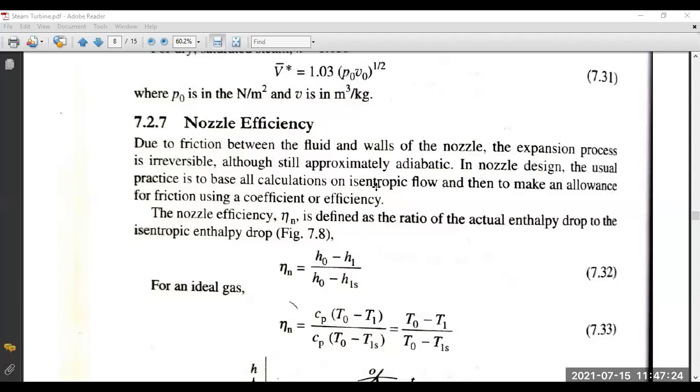This common point is where we get the enthalpy and the entropy of the stagnation point itself. So first we plot P0 from the Mollier diagram, then the P1 curve, and we put the curve of the temperature T0, and at the intersection we get point 0, the stagnation point.